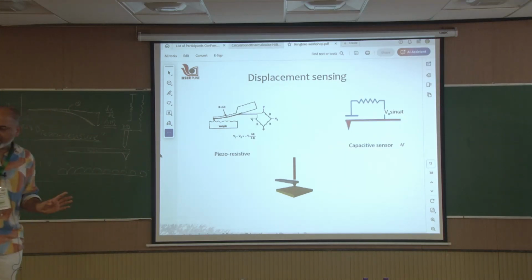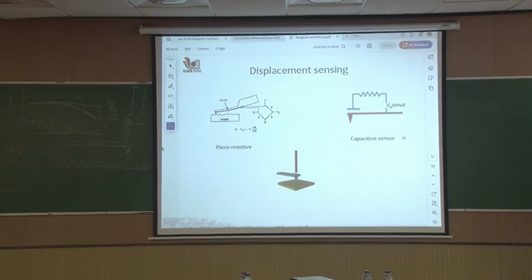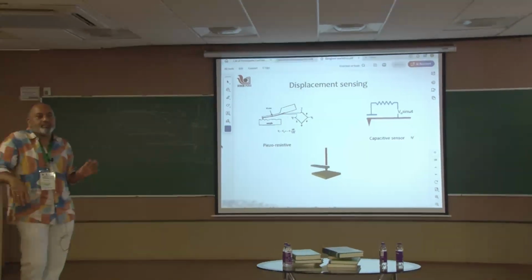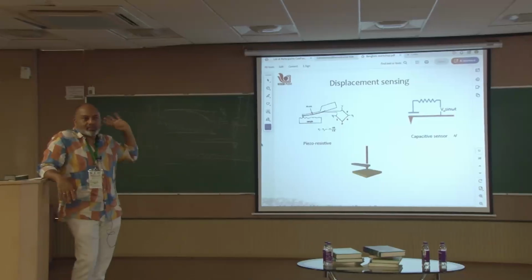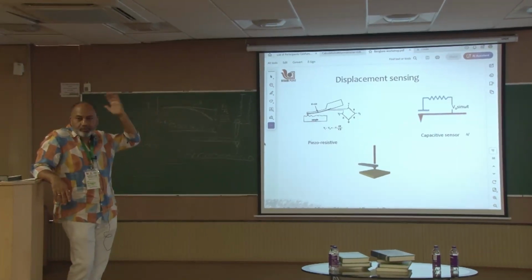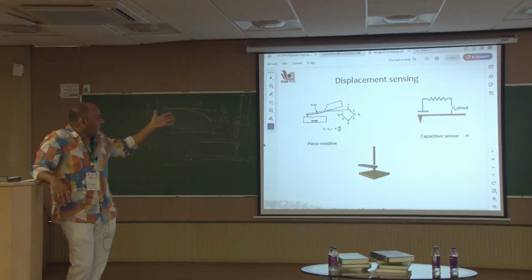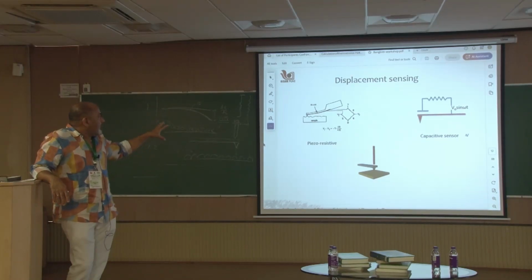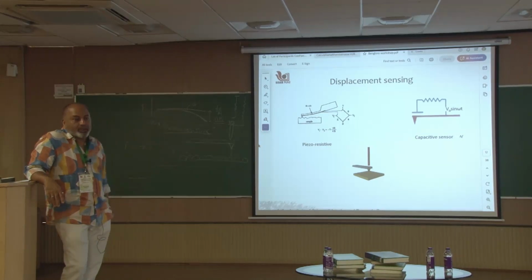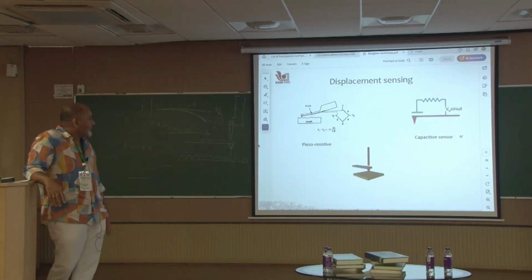This I have not used myself, piezoresistive I have used, but people say that it is very noisy, it picks up a lot of noise, maybe because of the RC network or whatever the reason. You could also oscillate the cantilever, but that's besides the point. That's another way of measuring the cantilever's bending, called the capacitive sensor.